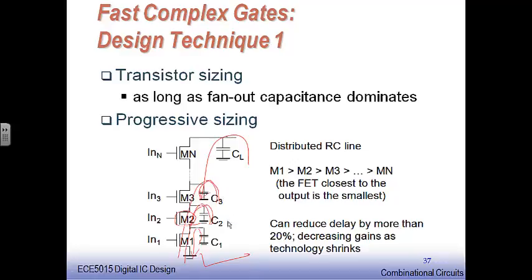So this way, if I look at the devices with equal sizes, they are going to be carrying different current values. Instead, M1, with its position of carrying the maximally possible current, I can make much bigger during the layout, and M2 with somewhat reduced current, because I am not going to have the C1 current going through that, so somewhat reduced size, the width for M2, and similarly for M3 I can do still some more reduction.